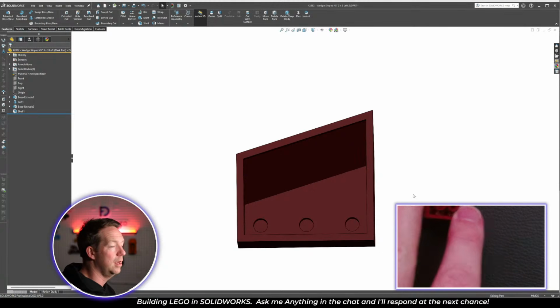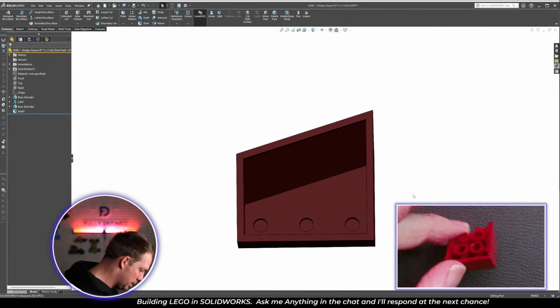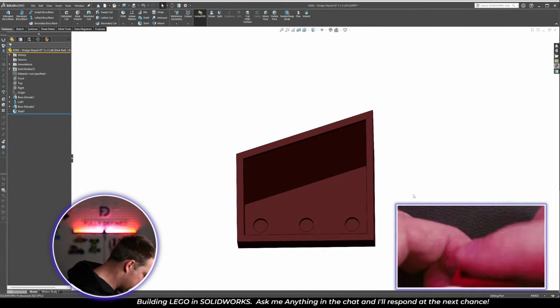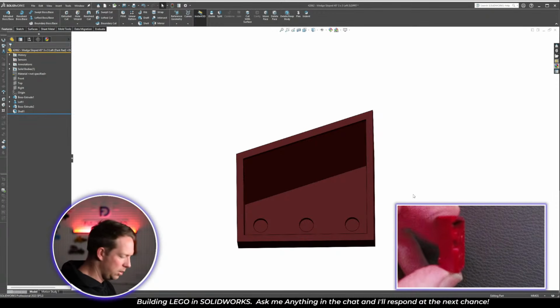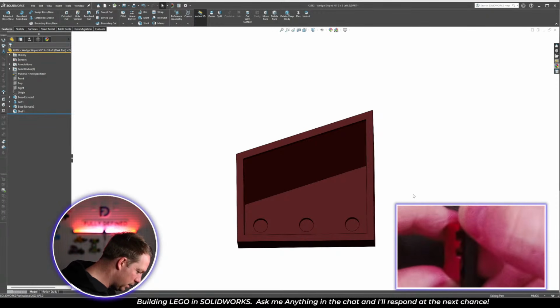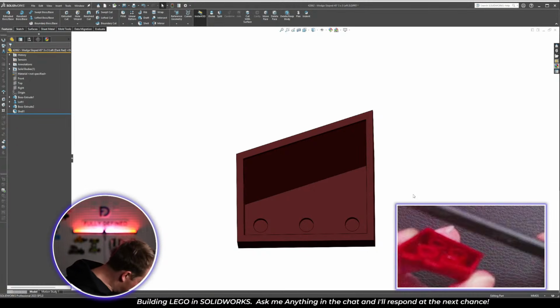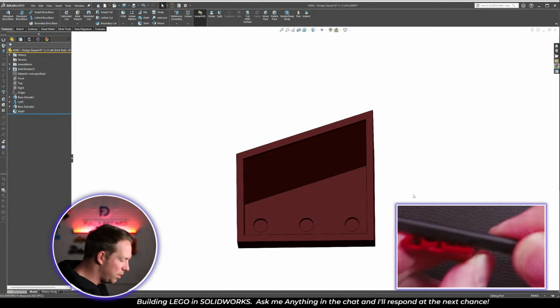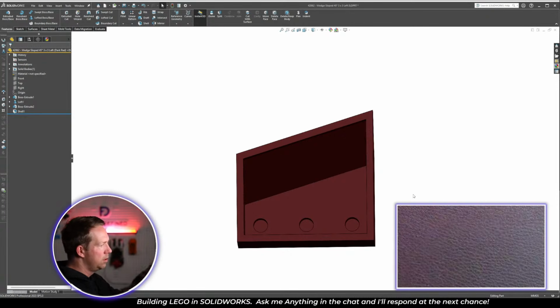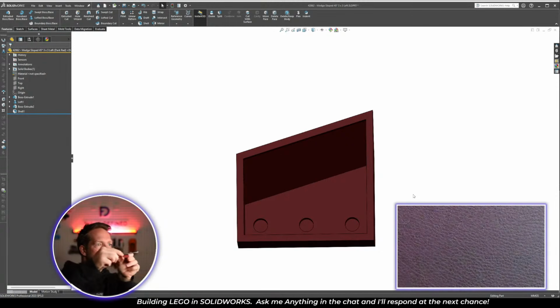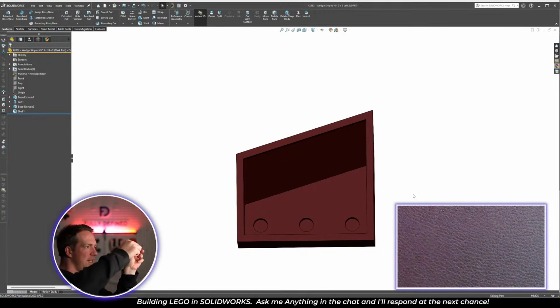Okay, so I've got the detail on the bottom to do. It's all very much just slightly below this top surface. Now we've got the opportunity to see it here because if you put a flat on a surface from edge to edge, and I can see light between what I'm holding on top of it and where those faces are, that means there's a gap.